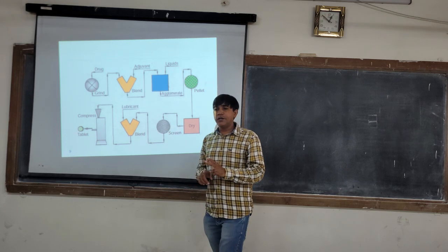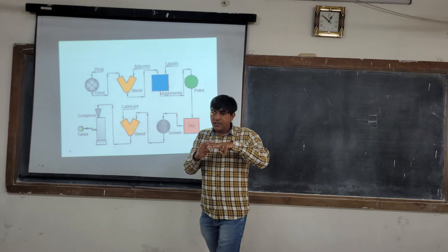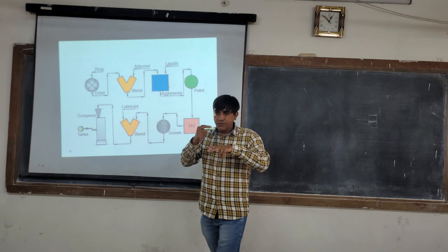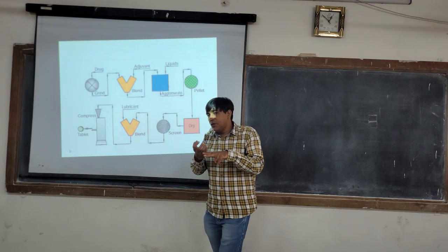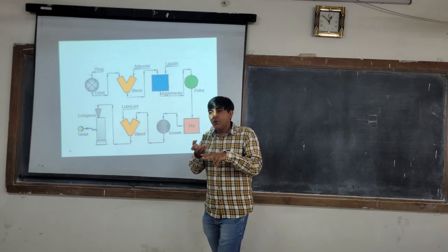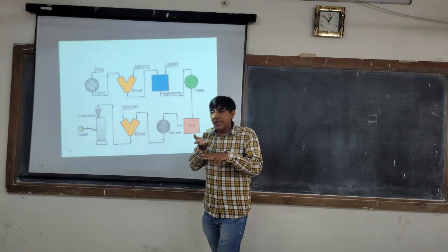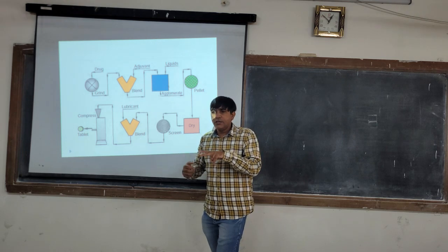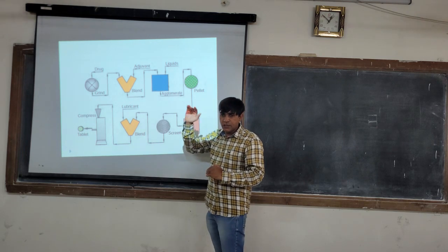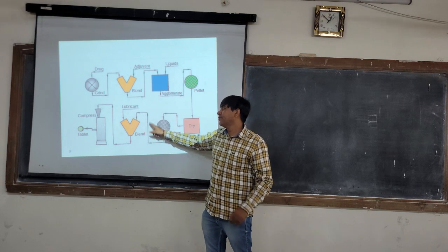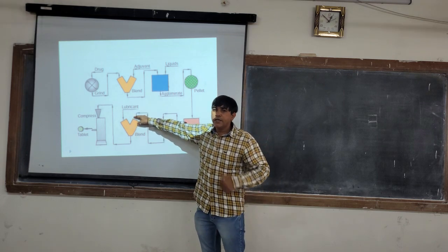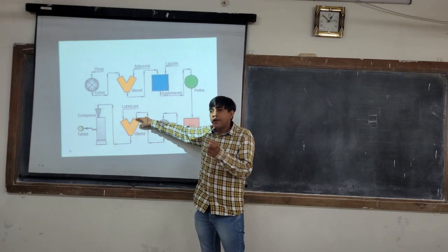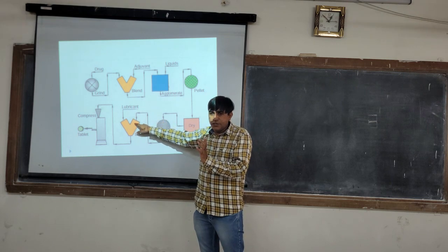Here, the screening is done for two things. We are rejecting the oversized, because sometimes there is formation of aggregates, and they will have a size more than that of the required size. Sometimes they shrink to form fines. So we are rejecting fines as well as oversized granules. We go for screening. Again, we blend with the lubricant, glidant, anti-adherent, and the extra-granular portion of the disintegrant.